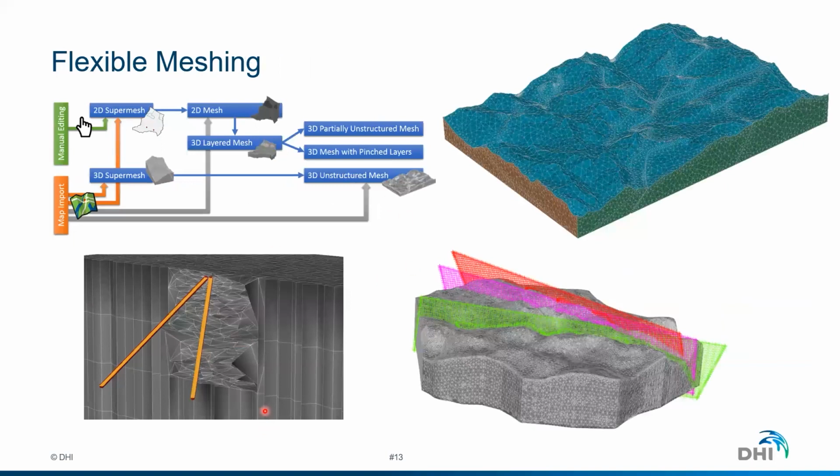Here is where we start getting more involved into the example of geothermal modeling, which I will discuss later. In some cases, when we are working in shallow geothermal, we might want to have simple models in terms of meshes, so we can build a FEFLOW model of our domains using some 3D representation and geological representation following some layers. You can build the discretization in 2D and then later extend the model to 3D.